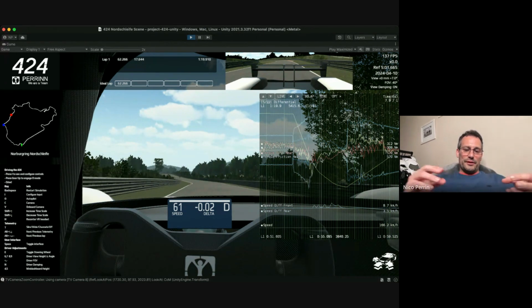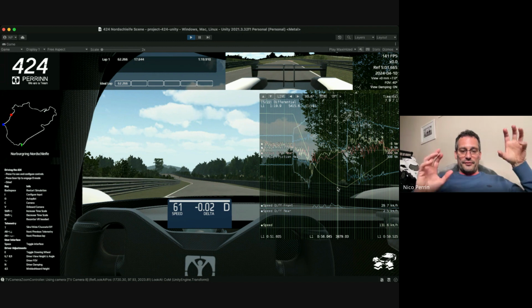And at that point, the torque across the diff reduces back to 0, and the speed across the diff is different, left to right. So we've modeled the diff very accurately because it's something I wanted, and I asked Eddie to make sure we have something really accurate here because it affects the car balance quite a lot.